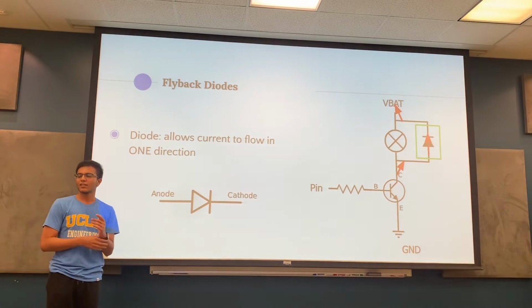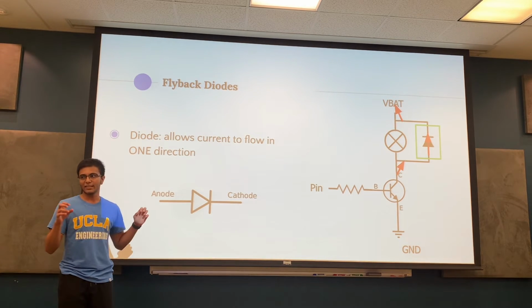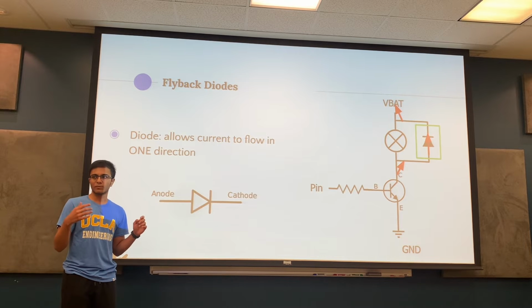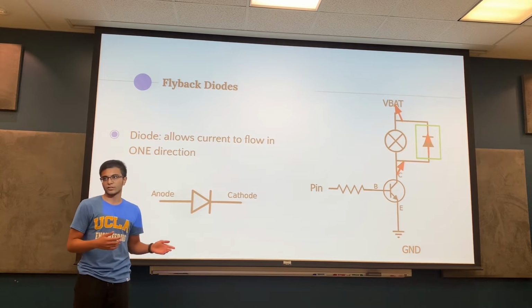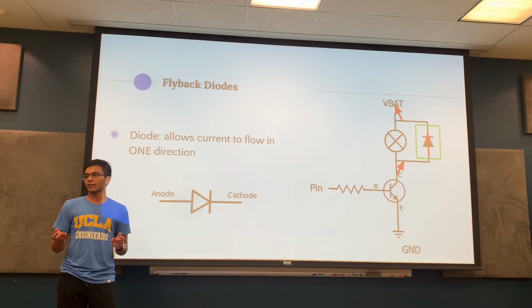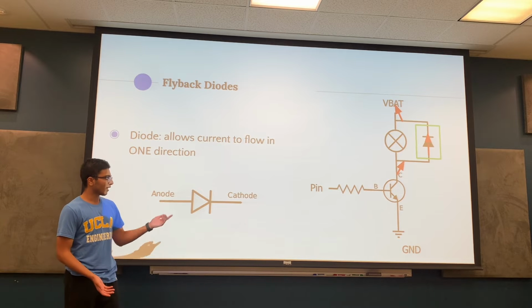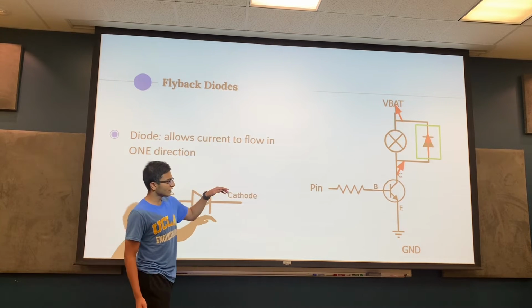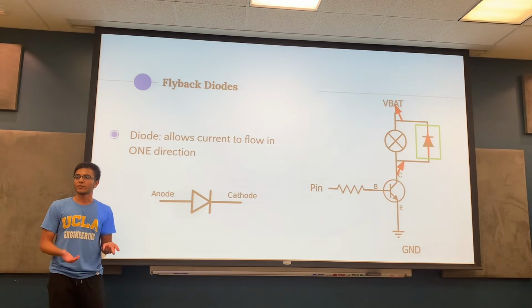You're going to learn about this more in your physics classes, but that's called back EMF, when the motor stops spinning. And to prevent that EMF from going into the microcontroller or harming the other ICs on the Micromouse, we have the flyback diode, which forces any back EMF to go back into the battery so that it doesn't harm the rest of the circuit.